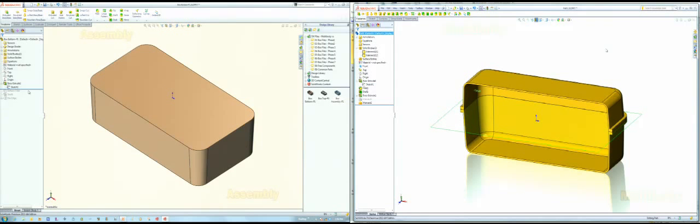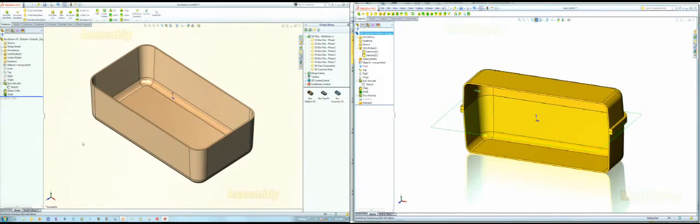3 inches, 3 degrees of draft, put a bottom fillet on it, and again on the bottom fillet there is a name on that radius. Shell it out, same as Phil, no big difference there. To make the lip boss all the way around, I did it a little different than Phil did it, because in this case we just used the sketch,